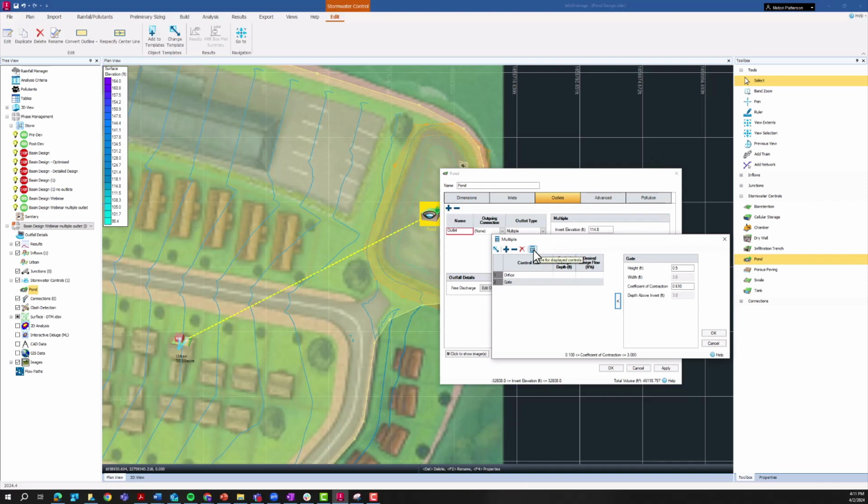There is also this solver here, and what this says is it attempts to calculate the parameters for each individual control that are needed to maintain the corresponding desired design depth and design flow. So selecting this option, it'll validate the desired design flow and depth, but it's not going to validate the individual control parameters.